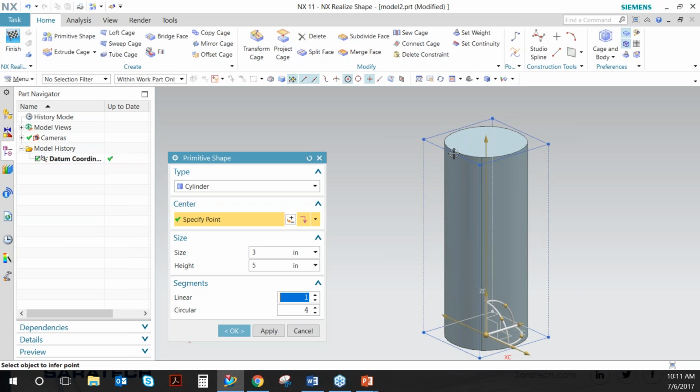We have one segment, which defines how the cylinder is spaced and broken apart, how many nodes you have essentially. And we can raise that at any point. So if you do linear segments, you can add and it'll split up the cylinder equally in however many parts you've asked for. Obviously this cylinder right here has been cut up into 4, which means they're spaced a quarter of the length each way. Now we're going to go back to 1 because we don't need that.